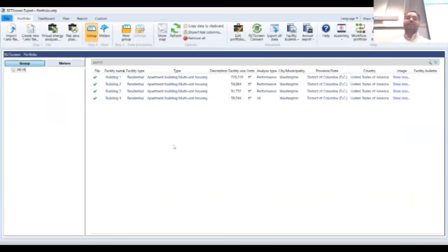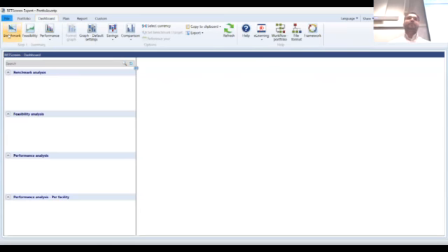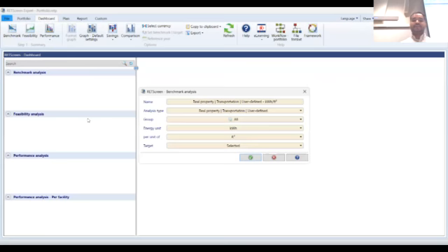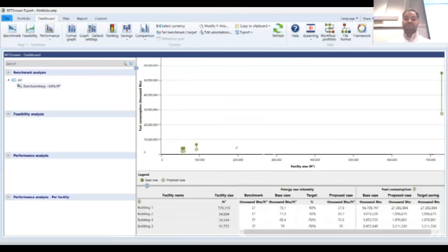So there are 4 residential properties that need to comply with BEPS. We have imported all the information that includes the area where the building is located, and the electricity and natural gas consumption for the past quite a few years. So the first step, we need to understand how a building is performing, whether it is meeting the BEPS requirement or not. So we go into the dashboard tab and plot a benchmarking graph to understand which properties are complying. I will just give it a name of benchmarking. I'm using the unit convention of kBTU per square feet, and I will be plotting a graph.